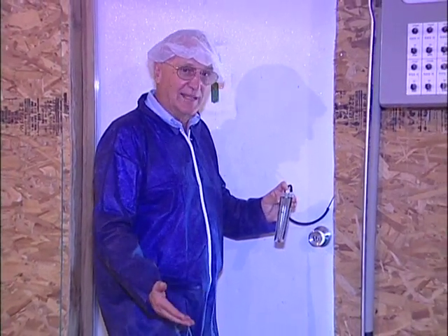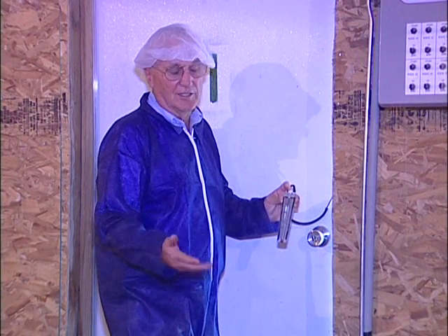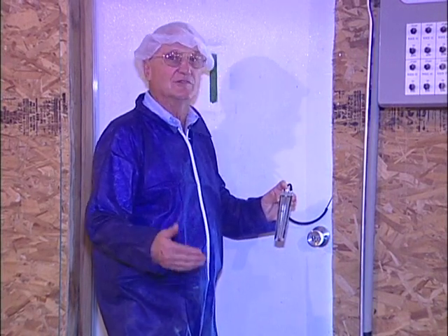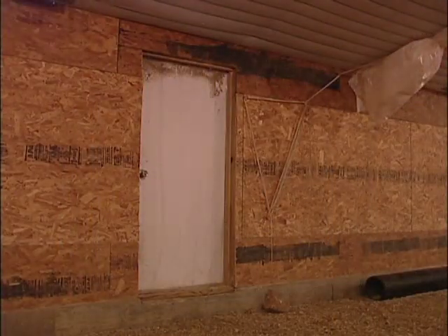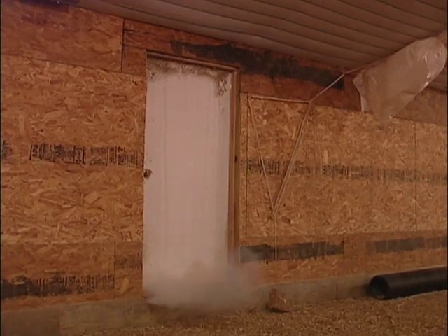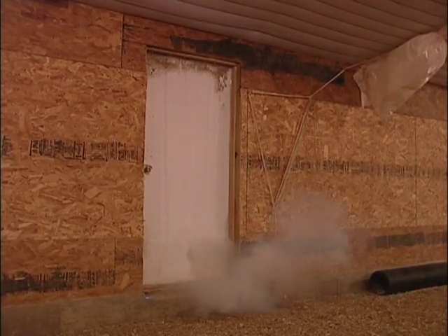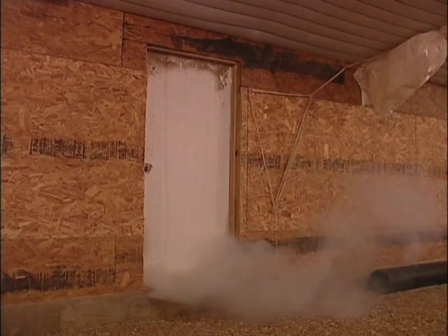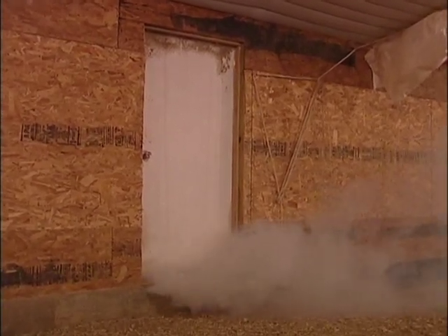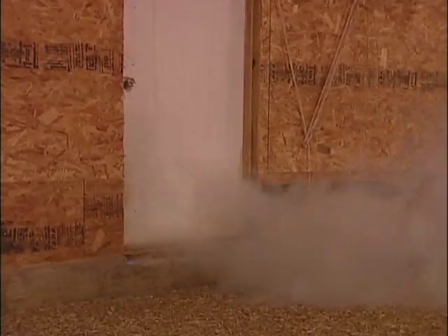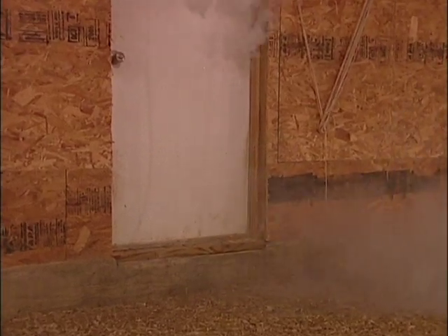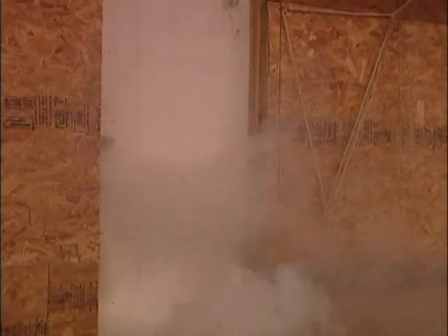You need to do the same thing to your inlet doors. You need to do the same thing to your end doors and your shutters on your summer fans. Now what we're looking at here is a walk-in door on the opposite side of the house from the control room. And even though this is a real good door, look at how much air leaks under the facing of the door at the bottom, and you'll see in just a minute up at the top of the door. So we've got to have that door sealed as well as possible, or too much cold air comes in and goes directly to the floor.